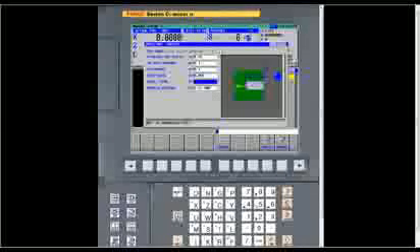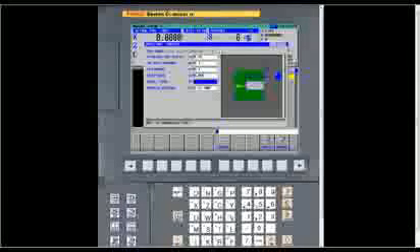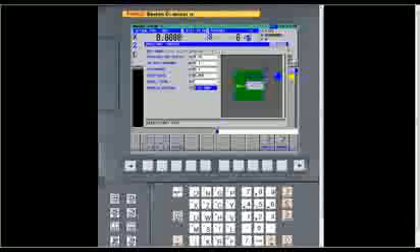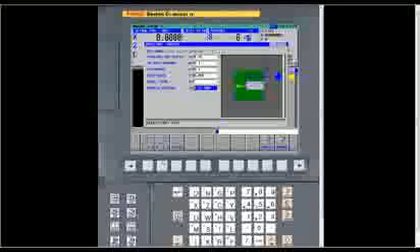Your feed rate, and dwell time, which again has an asterisk. You do not have to answer that information, but that's like dwell time at the bottom of the hole. If you wanted it to dwell for part of a second, you could put that in. And then the approach motion. Anytime the software will give you answers to any of these fields, there'll be soft keys down here at the bottom. So you have 3 different selections: a vector move, an X and then Z, or Z and then X.